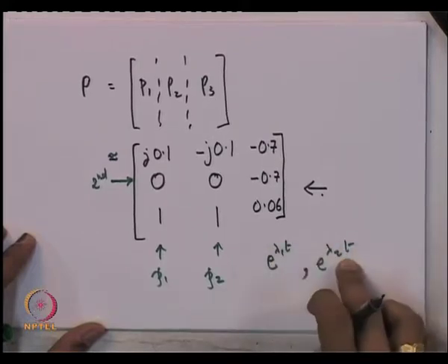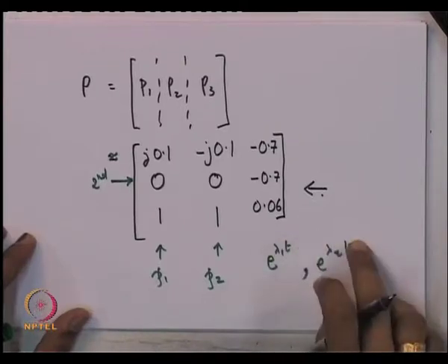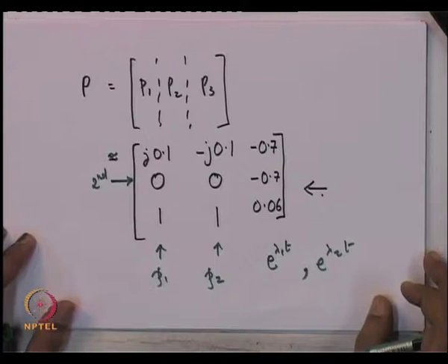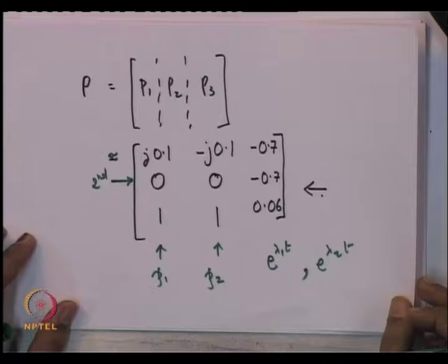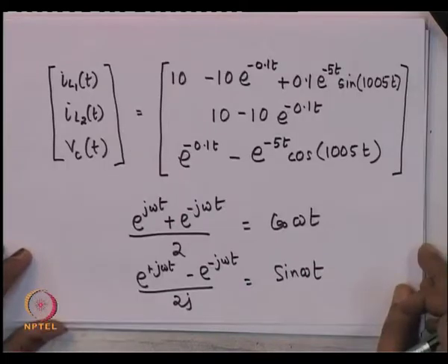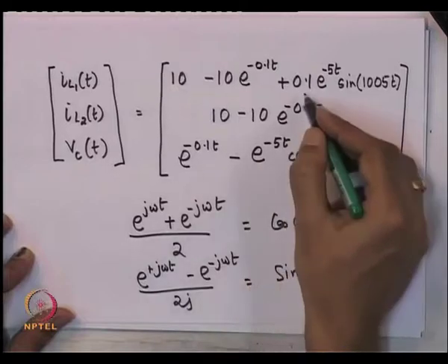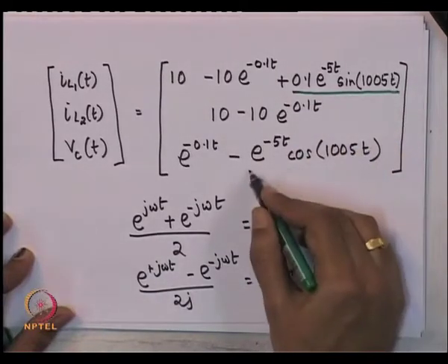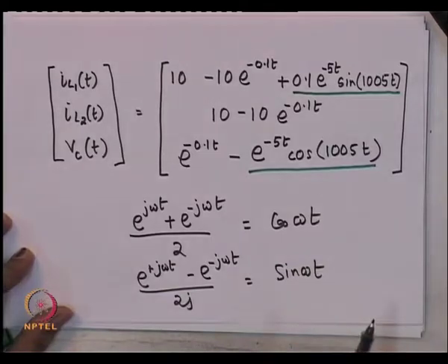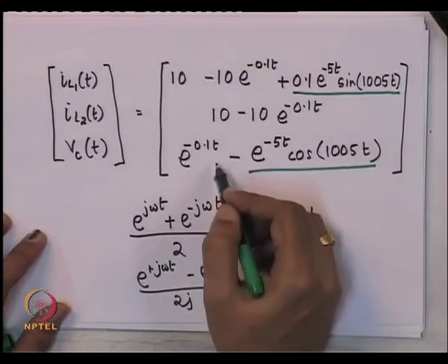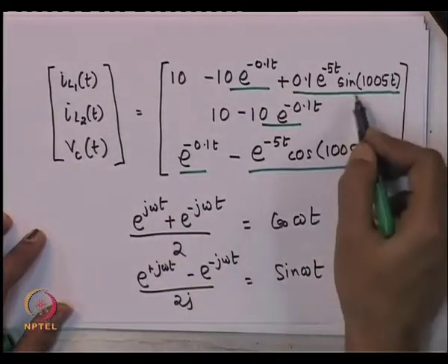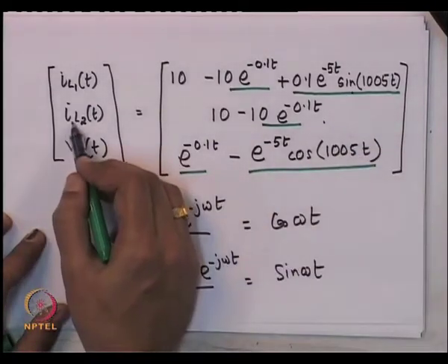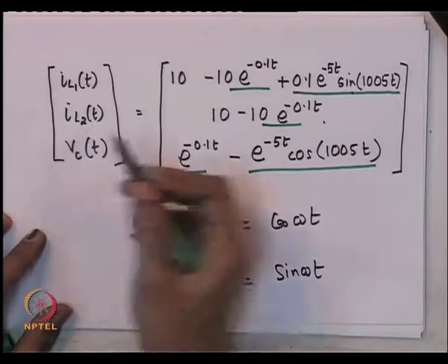In fact, lambda 1 and lambda 2 t were complex numbers. So, the first and second eigenvalues in fact point towards oscillatory response, and the final response of course was evaluated to be this. So, what do you notice here? Of course, here you have got this particular oscillatory response. This comes out because of the complex pair of eigenvalues, conjugate pair of eigenvalues. You also have this particular mode. This is practically not observable in the variable IL2.